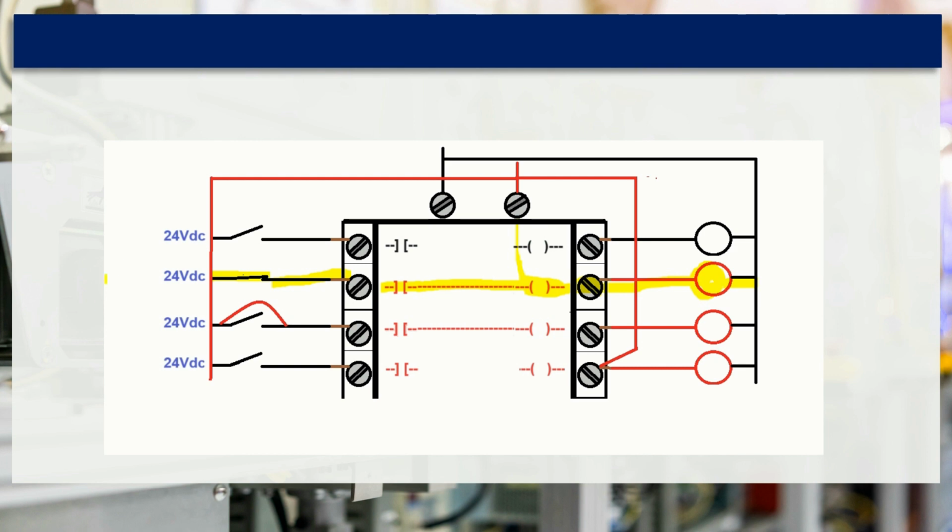Perfect. On our third one, we had a defective switch, so somebody said, you know what, I'm just going to put a jumper wire out at the switch. So they locked it all out, they put the jumper wire in, turned it back on, and lo and behold, the PLC sees the voltage there. It says, okay, that's true. I'm going to turn on my output because my logic's solved. Turn on the output, and the output gets energized. Perfect.